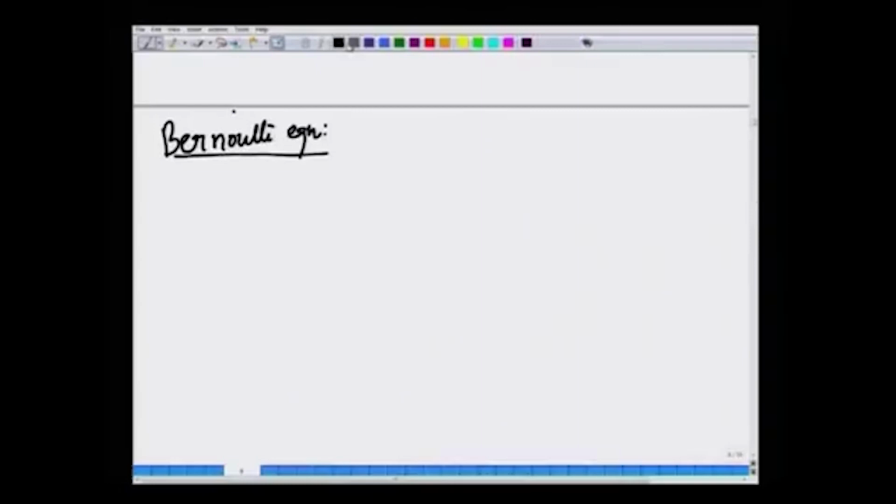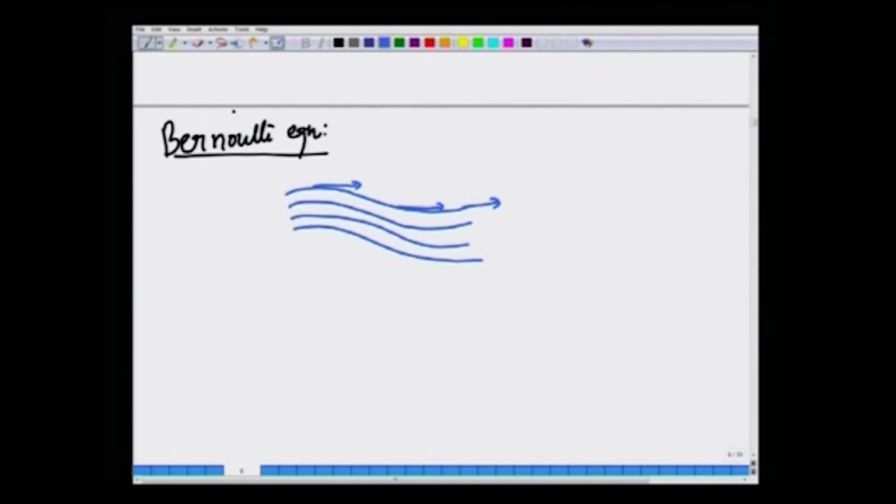Okay. So, in general, if you have a fluid velocity field, we define what are called streamlines. Streamlines are always parallel to the local velocity vector. Okay. So, in a steady fluid flow, you can describe the flow pattern using a bunch of streamlines by plotting the streamlines. If you collect a set of streamlines, you can form what is called a stream tube.